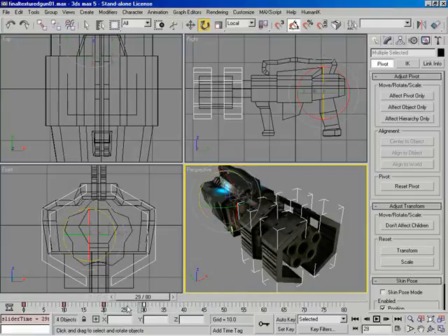Now I'm going to do the animation in reverse. We'll grab this keyframe over here where they slide back in, or excuse me, back together, and we'll simply holding shift down, click and drag it over to 40, and then I'll grab the one at the very beginning, shift click and drag it all the way over to 49 for a copy of it, and shift click, drag it over to 50 as well, because remember at 50, I want this guy to be completely closed back up, and then we'll go from there between 50 and 60.